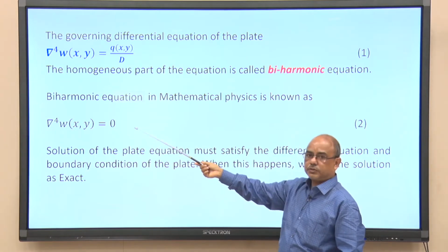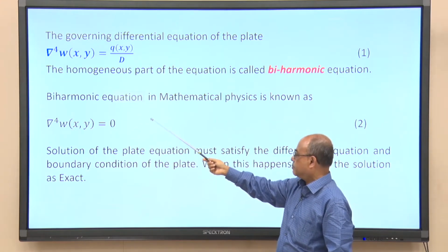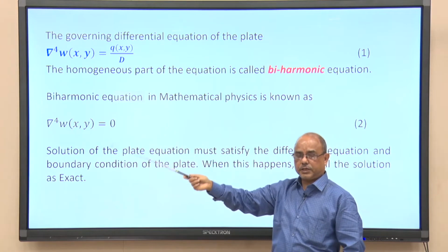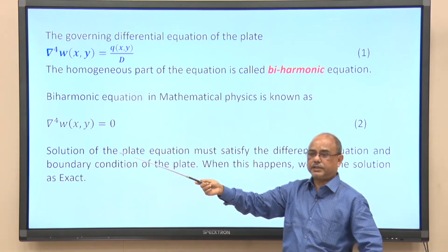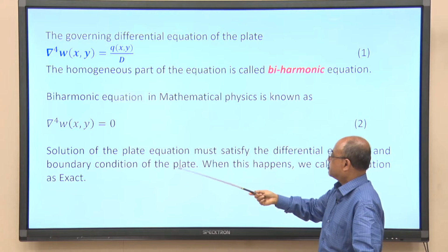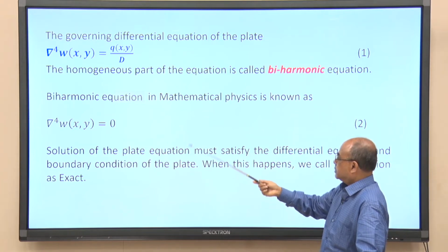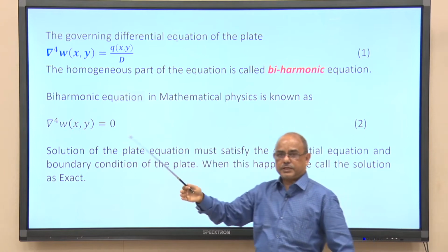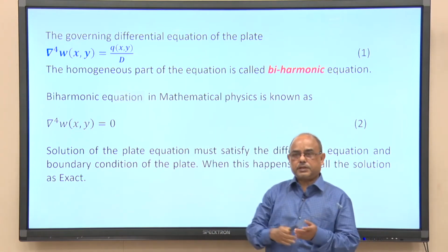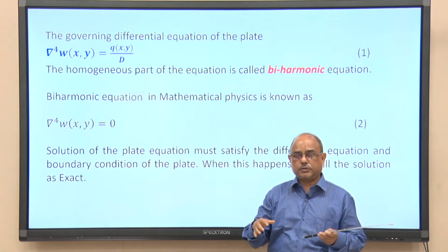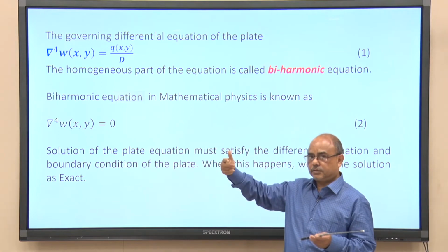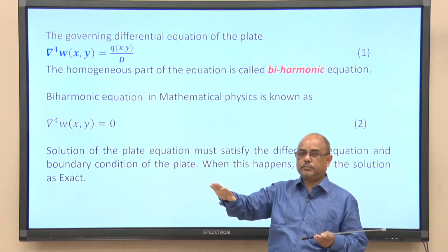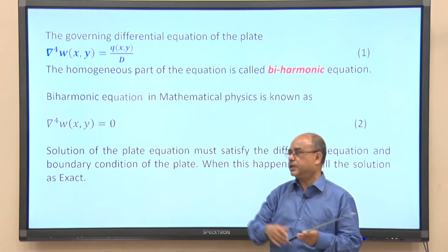So, the homogeneous solution for that type of biharmonic equation is already in existence in different theories of mathematical physics, and here if we go for the plate subjected to a transverse loading, or it may be some edge loading also, where the homogeneous part has to be solved, imposing the boundary condition at the edges.